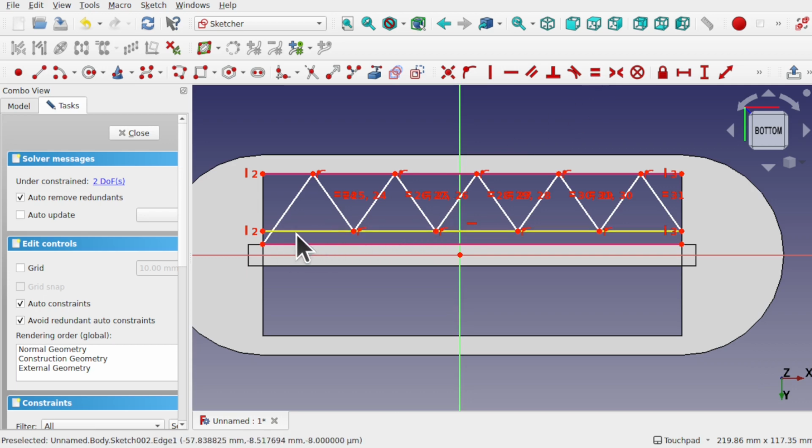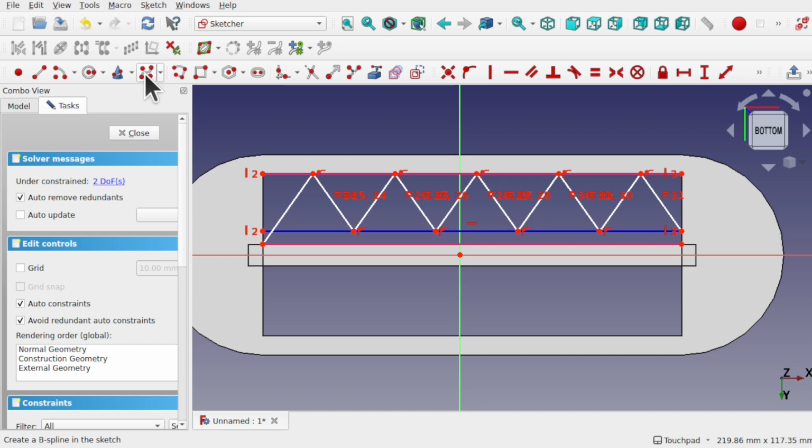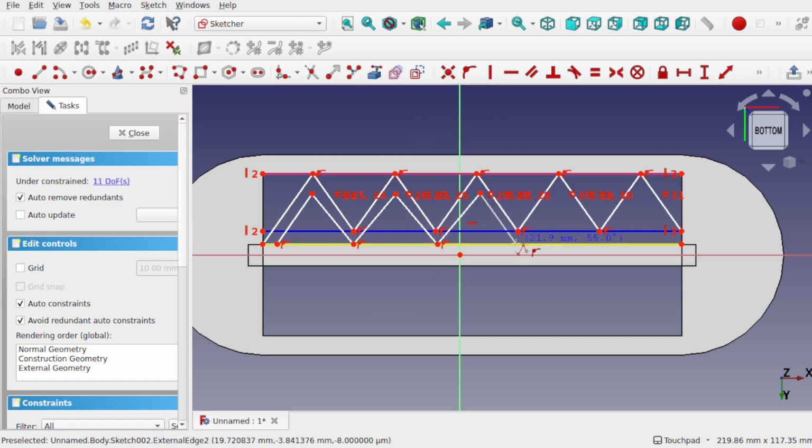So for this to be a closed sketch, we need to add another wall. So I'm going to come in here, connect up to this line and this one, and start sketching yet another set of zigzags. And this will close up this sketch. So just think that I'm doing this, and later on our framing failed, or I wasn't happy with the results, and I wanted to change this. So I change the configuration of the zigzags, or add more lines in here, more geometry to make it more interesting or a stronger pattern.